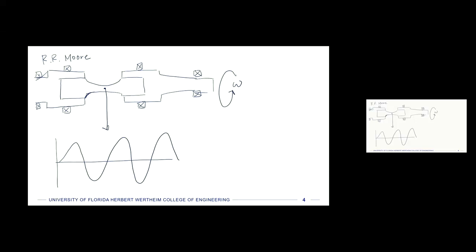So imagine you are a nanoscale person sitting on the specimen. As if the load goes down like that, let's say you start on the back side here, right? So when you start, you're in compression. Then as the thing rotates around, you rotate down to the bottom. Now you're in tension. Now you go back to the top, you're in compression. And that's how this sinusoidal curve is generated. So this is a rotating bending machine.